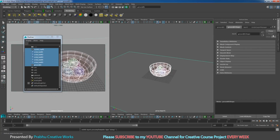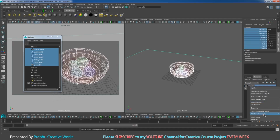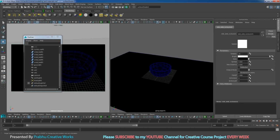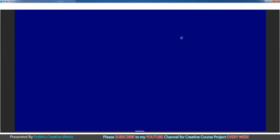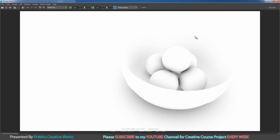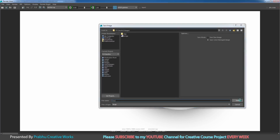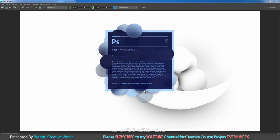Sometimes the preset will not be available. So right click and choose attributes, then right click and choose occlusion. Click on this checker. You want to give at least 64 samples and give maximum distance to 5. So I will click over here and click render again. Now you want to save this image. Go to file and choose save image, and choose OCC, that means occlusion. Then save. Now open Photoshop to comp our render images.